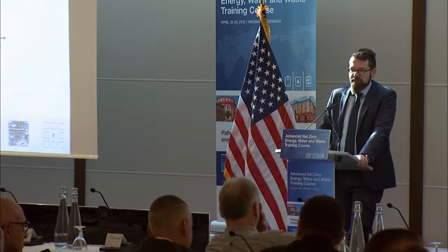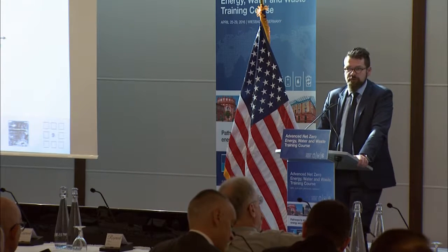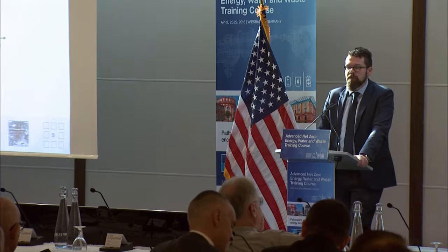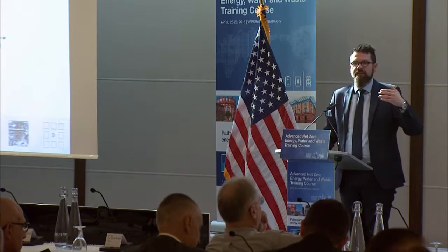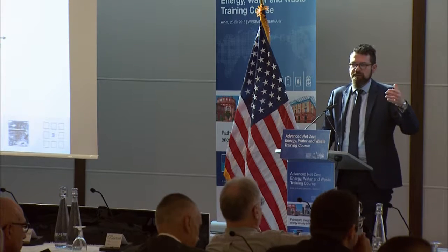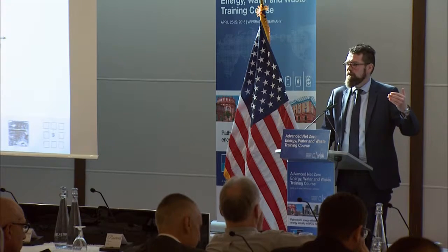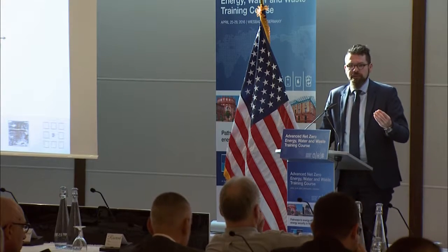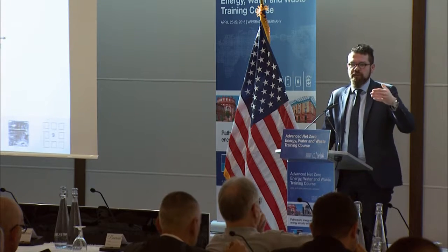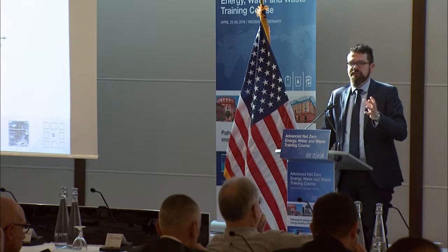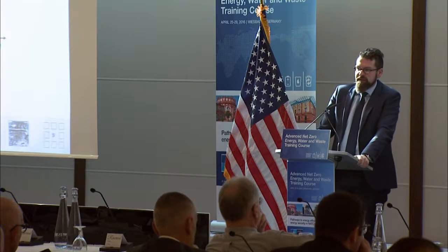The magnitude or height of the peak depends on the season and the outdoor temperature for sure. But mostly, in the morning, if people are leaving the house at 8 o'clock or 7:30, you start heating at 6 o'clock or 5:30 to warm up the rooms a little bit. Then in the afternoon, when you come back, you would like to have a warm room, so you start heating again around 4 o'clock p.m. And this is the second peak.